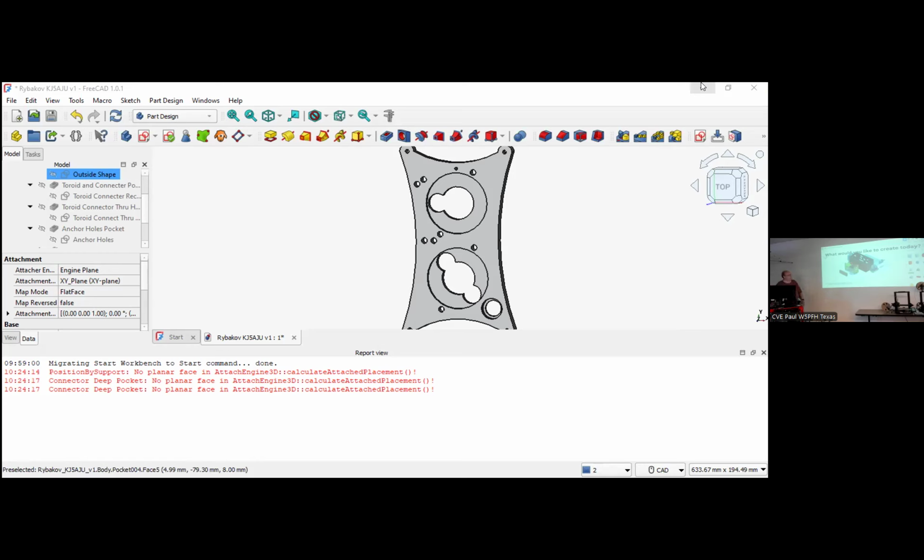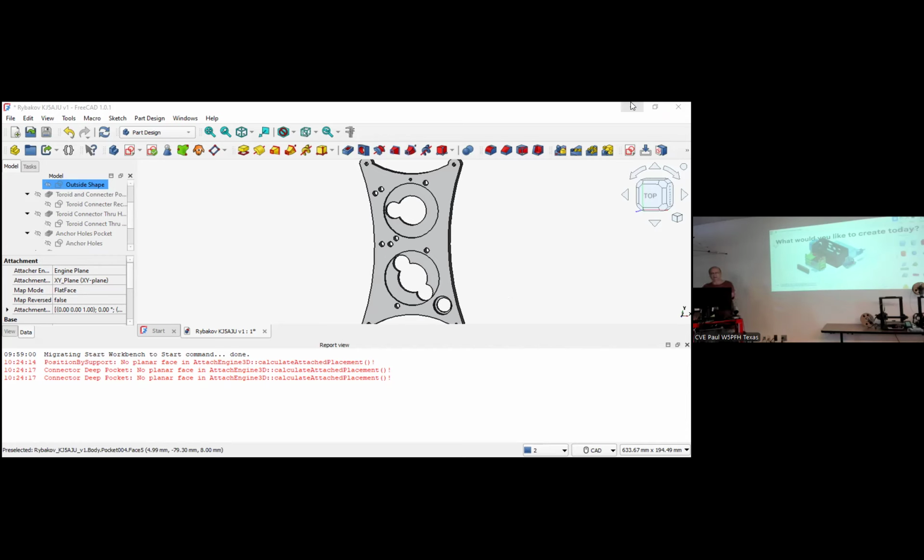The bottom of those 3 cards is a Raspberry Pi Zero 2W. The second card up is an audio card. And on the 3rd layer is a display, a custom board that I created for the push to talk circuits. And it'll basically do FT8 and APRS stuff.